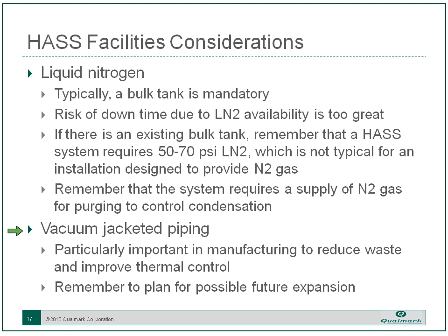And remember, as you put in that vacuum jacketed piping, to plan for possible future expansion. It isn't expensive to end your vacuum jacketed line with a fitting that will allow the line to be expanded later.